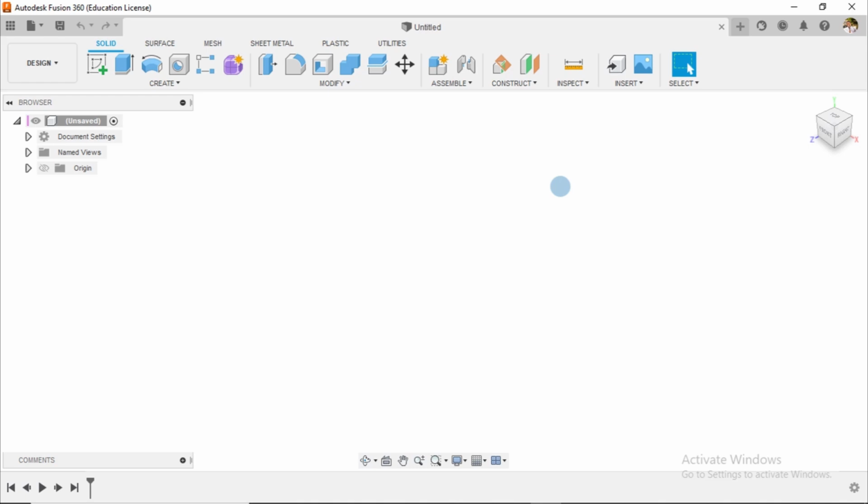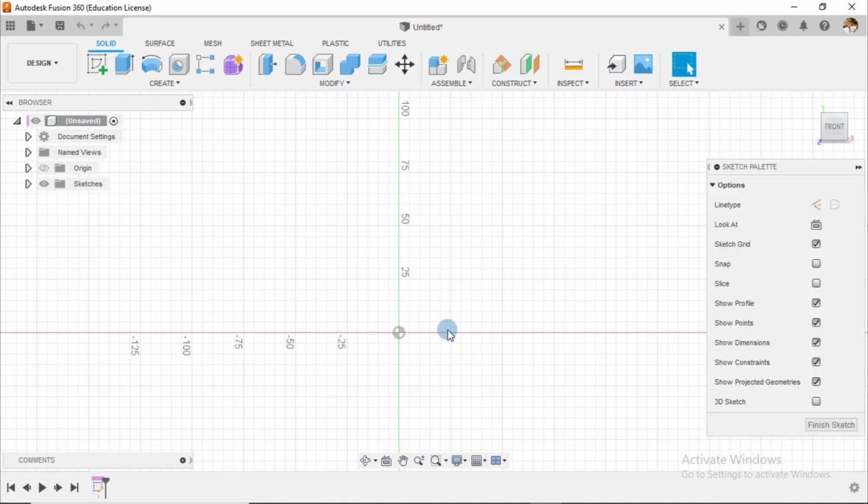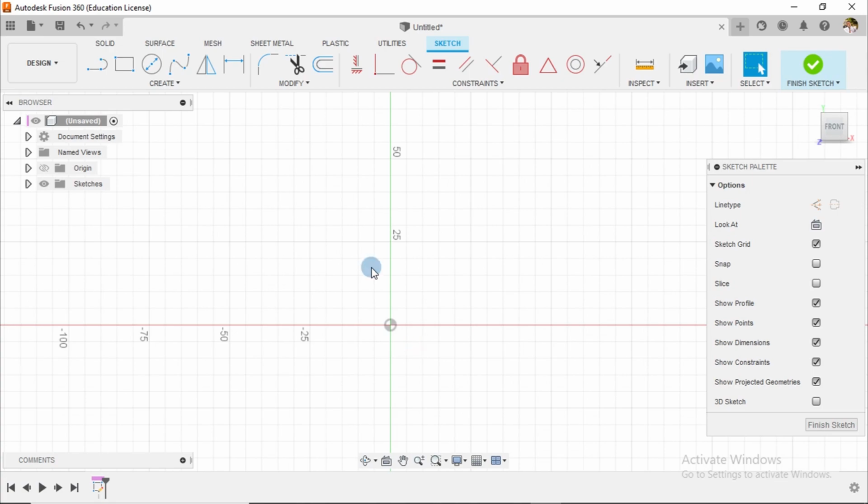For us to begin with this, we're going to begin by creating or using the sectional view, that's section AA. And so I would begin here by creating a new sketch, and our selected sketch is going to be this particular one. At this point, I guess that you already know that I just usually start by creating something that looks as appropriate as possible to what we intend to achieve at the end.